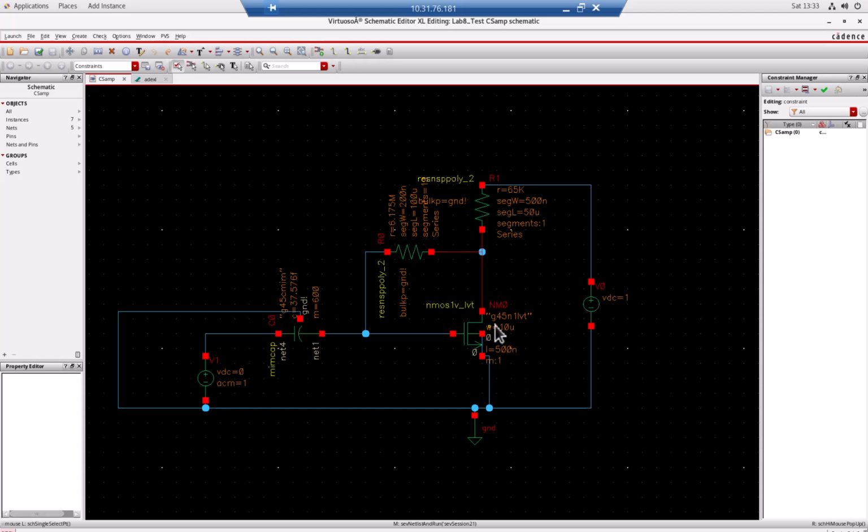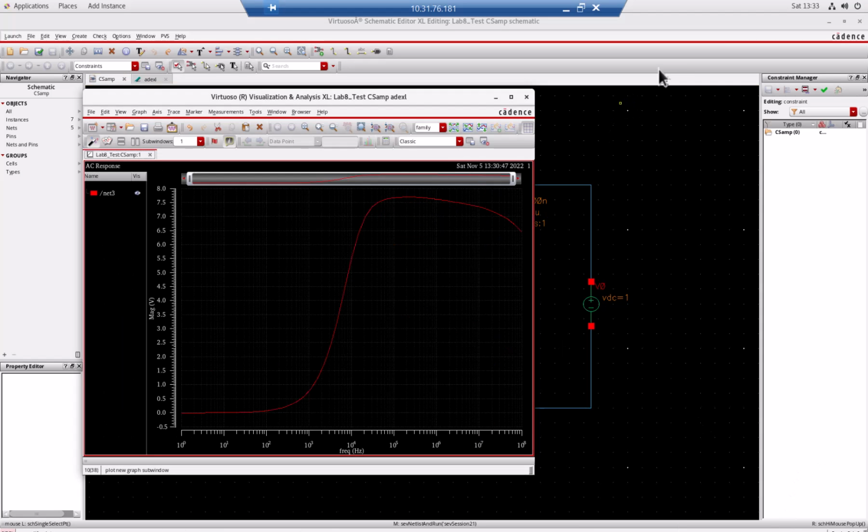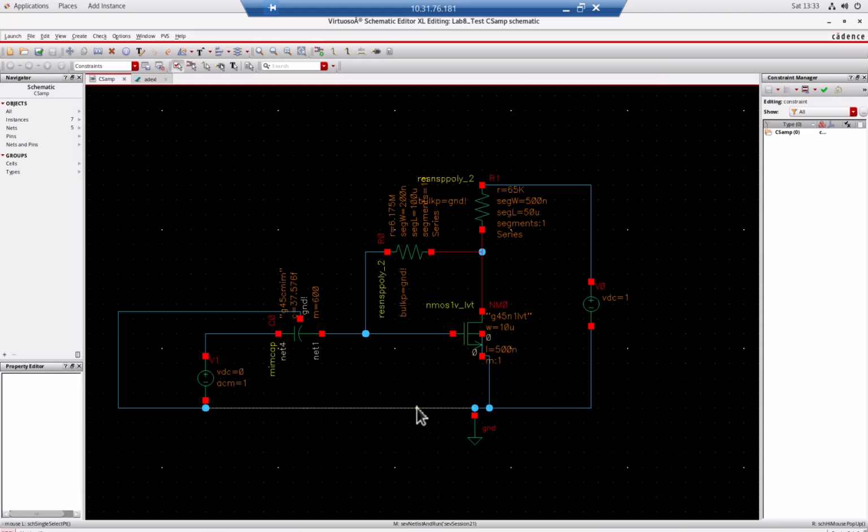And then based on the theory of common source amplifier, see if you get the correct gain at the mid-band, that is this region. And remember that when it is at mid-band, we can assume if we have a well-designed transistor, this one we assume is infinity, and we short this one and see if you get it to be gm (r0 parallel RD).